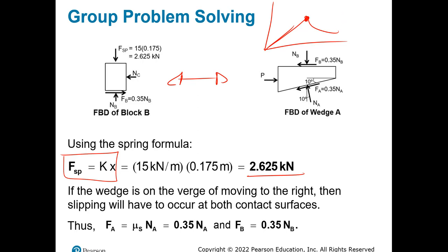When the object is about to move, it's right here, which is where the frictional force will be at its max, and you know that at its max it means mu sub s times the normal. Okay, and I'm just trying to show you how it's the same theory that we talked about at the beginning of the chapter, and that needs to be applied to all of the exercises when frictional force has to be